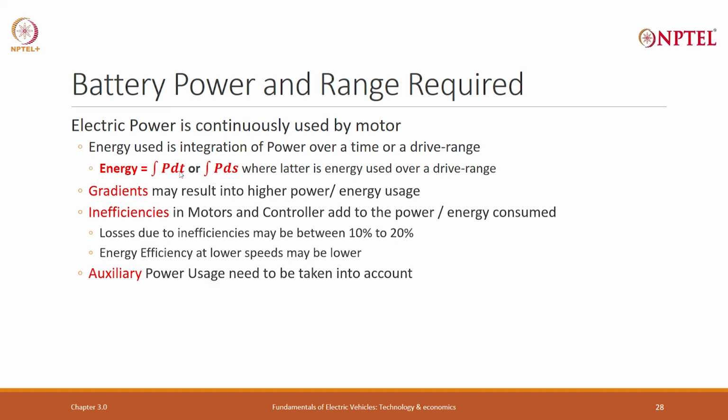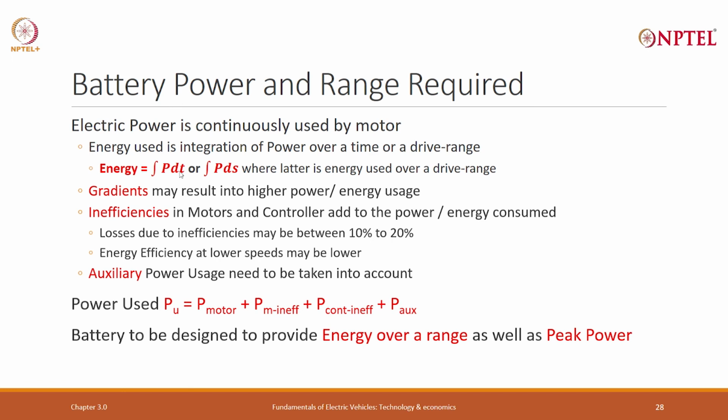Finally, auxiliary power usage can also take part of your energy. So, from the total energy, you have to subtract the auxiliary power, take out the inefficiencies, then figure out how much energy is available and whether your drive is good enough. Power used is power of motor inefficiency, power of controller inefficiency, power of auxiliary.